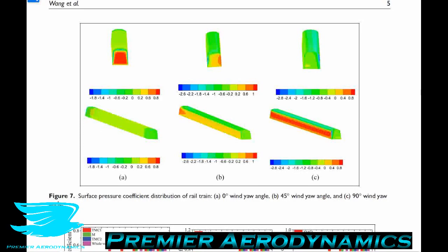These two results are very expected, because when the wind is hitting the side more and not the front, there is more deceleration of the flow, and hence a higher static pressure on the side facing the wind. So effectively, whichever side is facing the wind is going to be feeling a higher pressure, because you have all that kinetic energy from the dynamic pressure being converted into pressure we can feel on the surface.